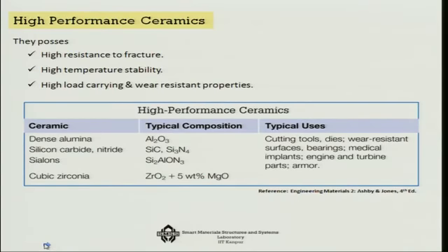Now there are certain high performance ceramics which have high resistance to fracture and temperature stability, high load carrying and wear resistant properties. For example, dense alumina, which is used in cutting tools, dies, wear resistance. Then silicon carbide or silicon nitride is used for surface bearings, medical implants. There is another product which is known as sialons.